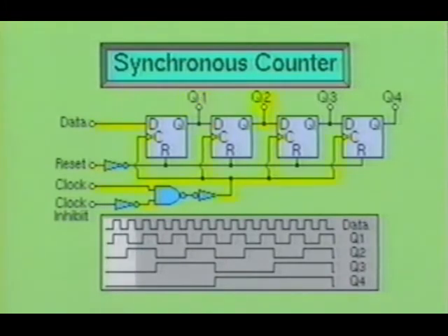Since the synchronous counter does not have nearly the propagation delay of an asynchronous counter, it is better suited for high-speed operation. However, some delay does still exist, and the actual operating speed is somewhat less than the maximum theoretical speed.